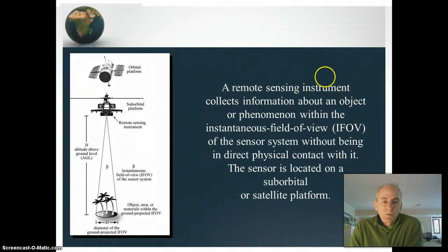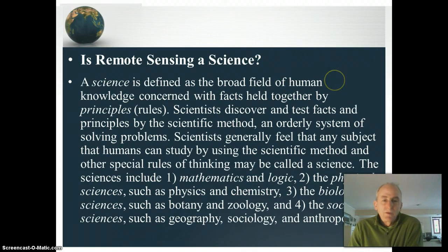And we know pretty much what a remote sensing instrument is, and we're usually concerned with the instantaneous field of view, which determines in most instruments what the size of a pixel is. So usually when we're talking about the IFOV, we're talking about the pixel size, which ultimately gets represented as a square or a rectangular raster.